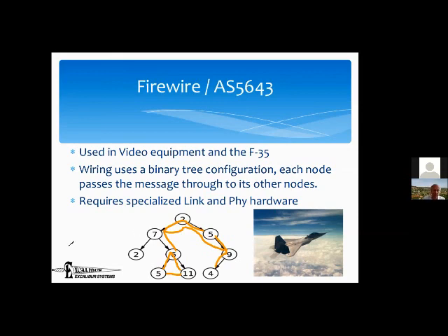So it's a little bit more robust than 1553 because of the multiple paths, and it doesn't require a bus controller, which means that's one less single point of failure, but it's really complicated. In the hardware and the software, there's a lot of very specialty stuff going on, which makes it complicated, and complicated translates into expensive.